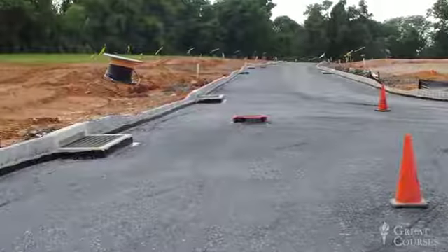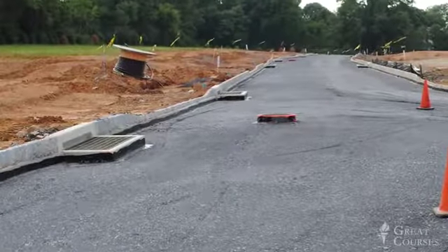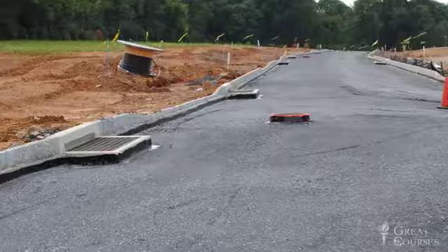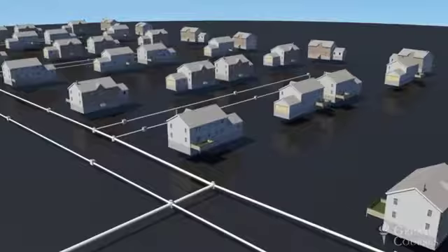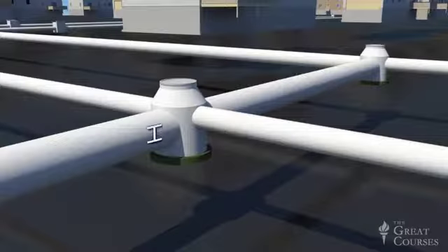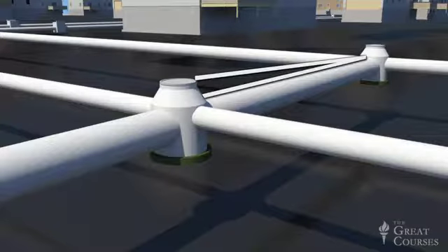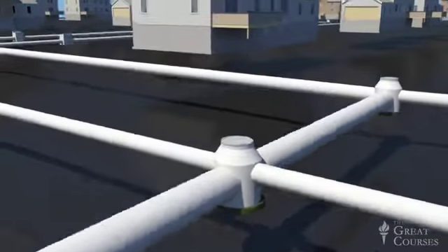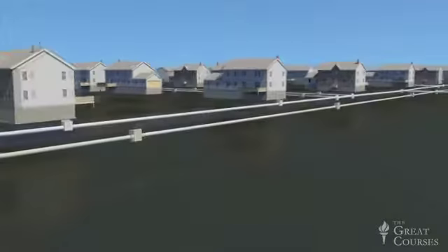Additional inlets are often added at regular intervals to intercept the flow so the inlet structures at the low points don't get inundated in large storms. With the inlets positioned, the science of hydraulics provides us with all of the analytical tools necessary to determine the size of each pipe such that it can carry the accumulated discharge from the inlets and higher level pipes, and the slope of each pipe such that the velocity of flow is high enough to prevent sediment from accumulating in the pipe. It's both surprising and impressive to see how much engineering goes into a system that's almost completely hidden